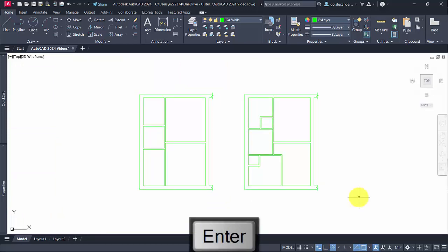So that's the way the walls, both internal and external walls, have now been done, and it's important that you add the break lines just to indicate on both floors that it is a semi-detached house and the construction continues, probably as a mirrored image.